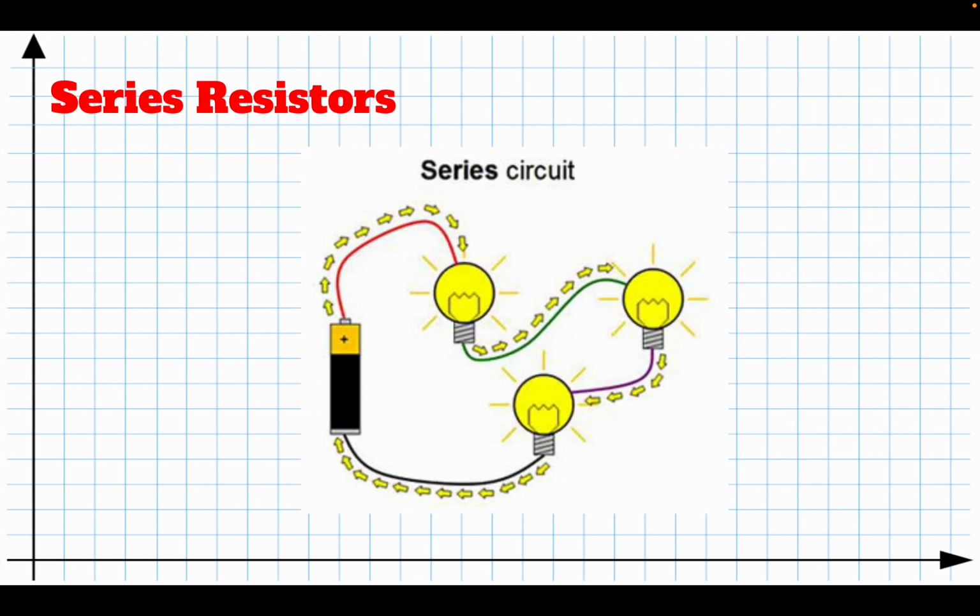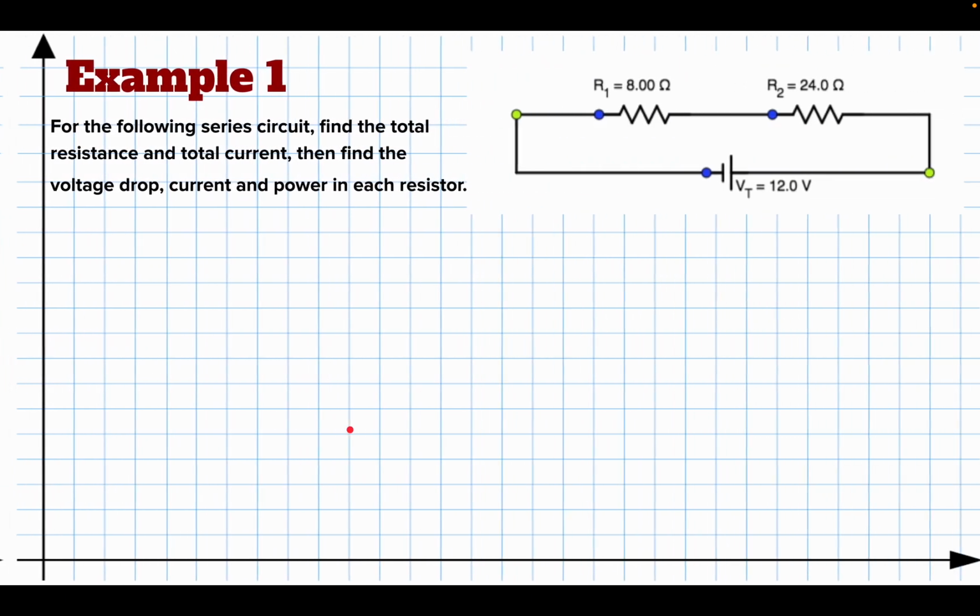So you know you have a series circuit when the current goes through one object and then the next and then the next. Okay, so think Christmas lights. If one of these bulbs burns out, if this little filament melts, then the entire circuit goes dark. The current stops flowing. You have to have a complete circuit to make this work, and if any one part fails, then the entire circuit goes out. So that's like Christmas tree bulbs.